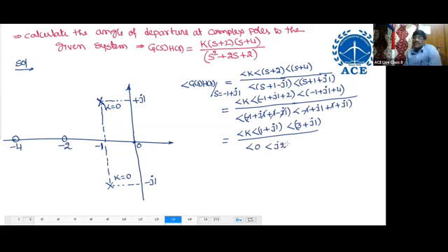So come on, write how to find angle. Tan inverse of, I told you the last day, based on which region the point exists, you have to write the angle. If it is the first region, simply tan inverse of imaginary part by real part. Second region, 180 minus tan inverse. Third region, 180 plus tan inverse. Fourth region, minus tan inverse of imaginary part by real part. Angle of K is 0.